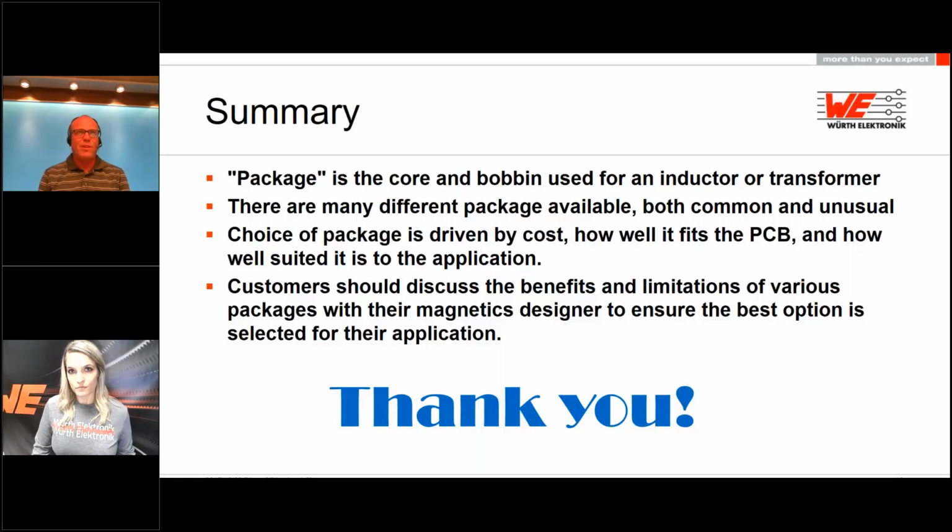So with LLC, you actually typically need to increase leakage inductance. This is done by adding space between the windings. So for example, instead of having your primary and secondary windings wound concentric on one side of the bobbin, you'll split the bobbin into two sections and wind the primary on one side and the secondary on the other.